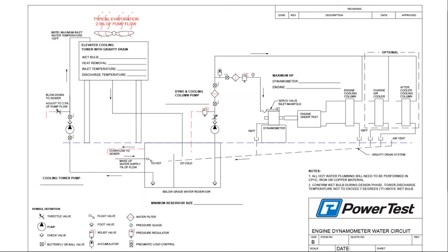If you're overseas, typically it's 380 volt, 50 hertz, 3-phase, and 220. If you're in the States, typically it's 460, 3-phase, 60 hertz, and 110 single-phase, 60 hertz. So we provide the material you need for the pumping process, cooling tower, etc. on the system. But I think the big thing is this gives you an idea of what would be provided with a quotation. I'm going to walk through it once. So this is made specifically for you.